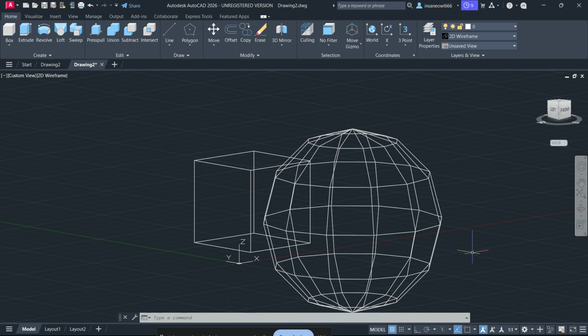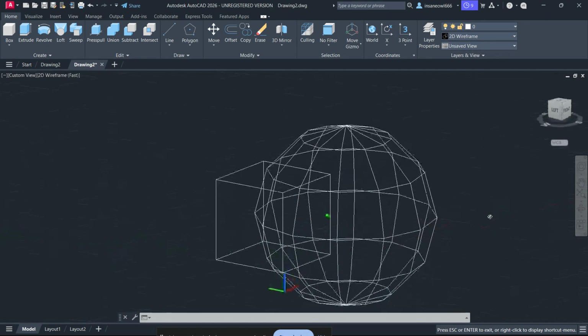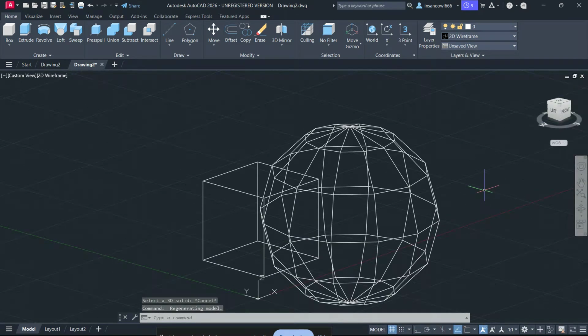Another very effective workaround is to simplify the geometry before combining the objects. If your model has complex fillets, chamfers, tiny threads, or highly detailed curved features, remove them temporarily before running the Boolean operation. These small details often create the exact kind of intersection confusion that causes error 97008. Once the main solids are successfully joined or subtracted, you can reapply the details afterward. This approach is especially helpful in mechanical drawings or imported models with a lot of surface complexity.